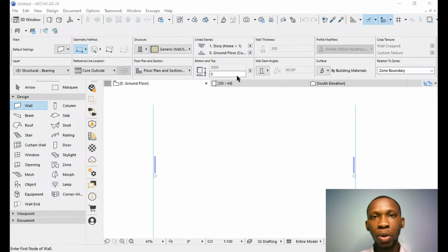Let me go back to the place where we saw this. So we use this particular tool. We did this from the documents option. Is it the documents? Yeah, from documents. So now when you go to documents, you go to floor plan scale. Click on it and then we set the scale for this drawing. Let me change this scale now and you see what happens to the size of this drawing I'm working on. Let me select scale 1 is to 500 and I click OK.